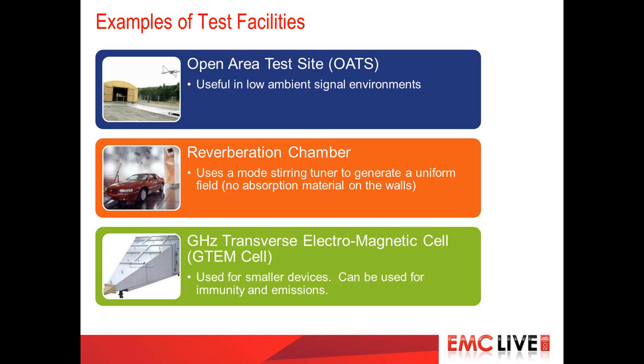Okay, great. What's a reference bandwidth? So reference bandwidth, that's a term that CISPR uses. CISPR is essentially an international organization, and one of the documents that they've defined, CISPR 16, is all the requirements that a receiver needs to meet to be commercially compliant. And in that document, they call out specific reference bandwidth.